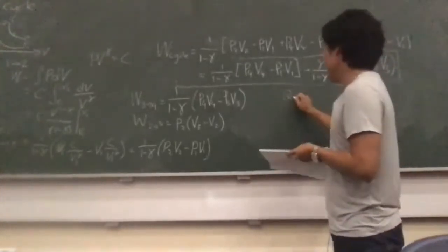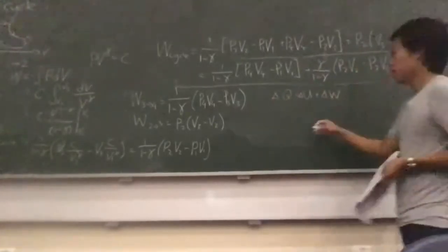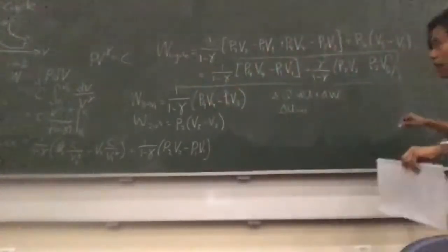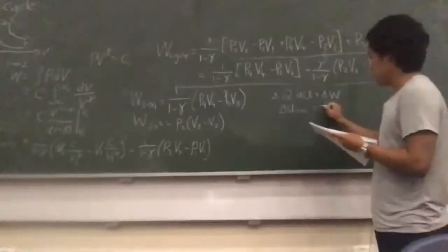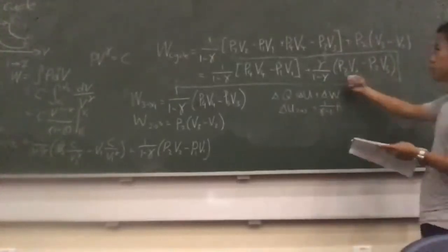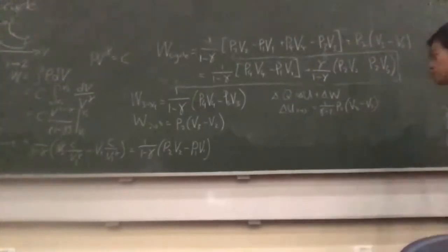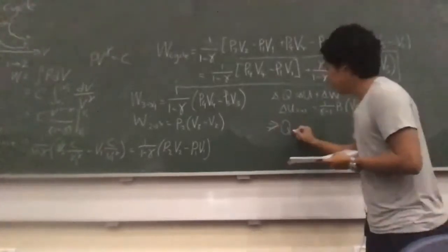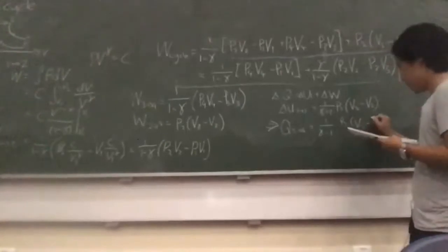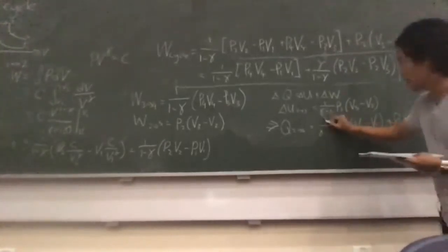So the same thing as before, heat going from somewhere is always going to be the changing internal energy plus the amount of work done. So using this, we first work out the heat from the changing internal energy from 2 to 3. So going from the easy one, the isobaric process first. So from 2 to 3, from isobaric process, you know this is just 1 over gamma minus 1 times P2 or P3, depending on which one you want to label. But I think we replaced all P3s with P2s up here, so best to keep it consistent. And then the delta V, which is just V3 minus V2, because everything else is constant. So then, therefore, the heat flow from process 2 to 3 is equal to 1 over gamma minus 1, P2 V3 minus V2, plus P2 V3 minus V2. So this just adds another factor of gamma here, and you can forget about this term.